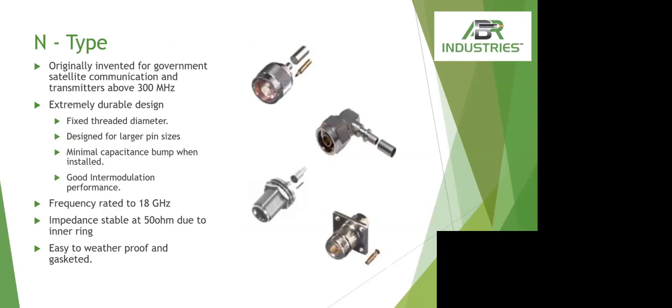Next is the N-type connectors, typically built for the government for satellite communication and transmitters above 300 megahertz, because for a long time we thought 300 megahertz was the end of the RF world. Extremely durable design, a very constant impedance, designed with a larger pin so it can handle the bigger size coax cables like the 400, which is a larger center than an RG213, for example. A very minimal capacitance bump when installed, and very good intermodulation. A lot of N connectors are rated up to 18 gigahertz. They're very stable, like I said, because of the inner ring, so the impedance never switches and moves. And then they're very easy to weatherproof because they have a gasket that's built into them.